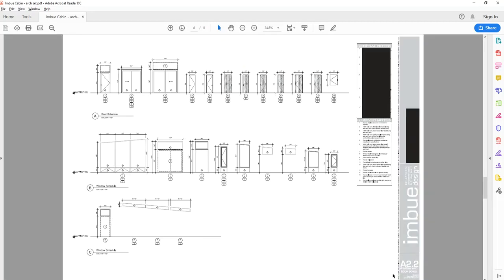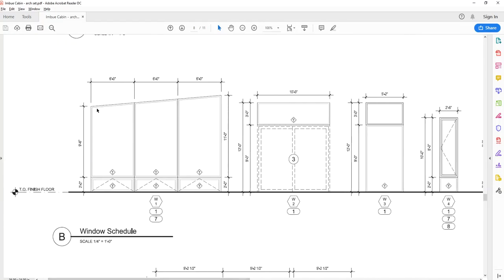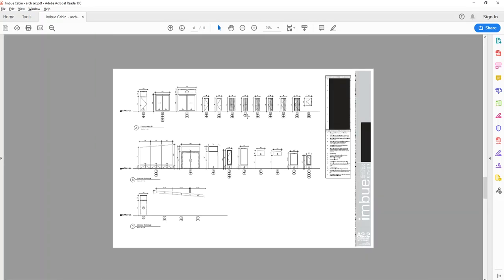Use this A2.2 window and door types sheet to see how big these windows are and how tall they are. I think it's completely appropriate just to say for this window right here, we'll just do a square window. We'll encompass the whole thing, which means it's going to be 9'6" plus 2 foot. So that's 11'6". It's a big window, right? By 6 foot. So we'll have 3 of those, but don't worry about having this piece on the bottom and this piece on top and it angled. Just do one rectangular piece of window. Okay, I think that'll work just fine for this case.